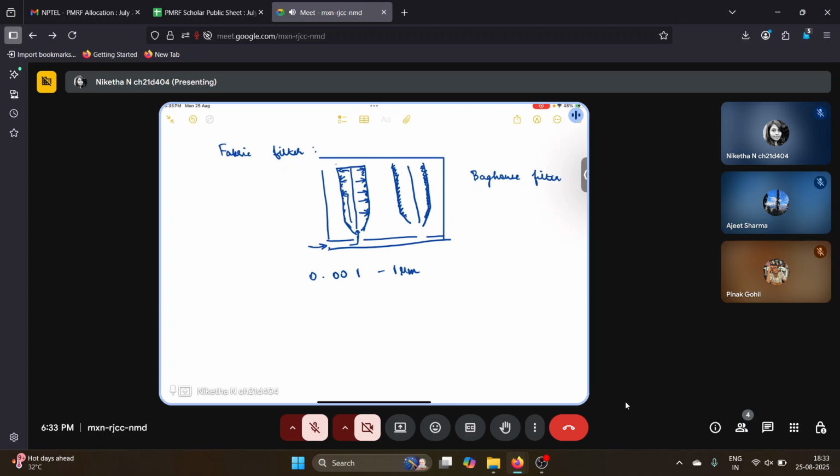So we bring out these filters one by one and shake them. If there are huge filters, most of the time these containers are inbuilt with shakers. They just shake the bag filters, and they remove the attached particles, and then the dust is collected at the bottom. So here we have something like a dust collector.